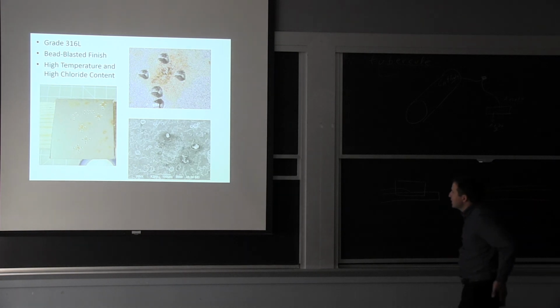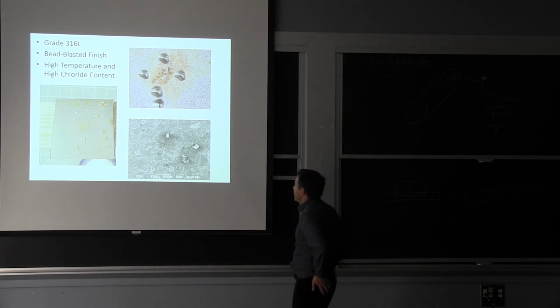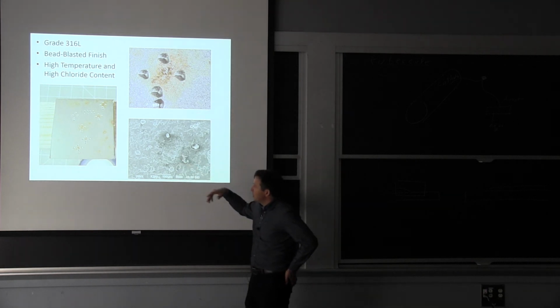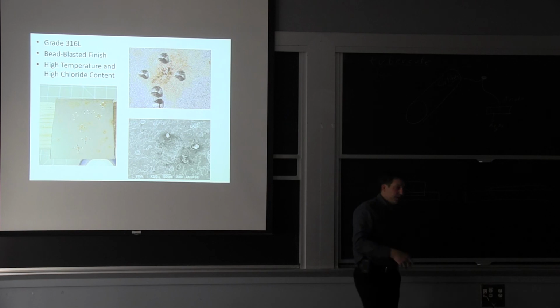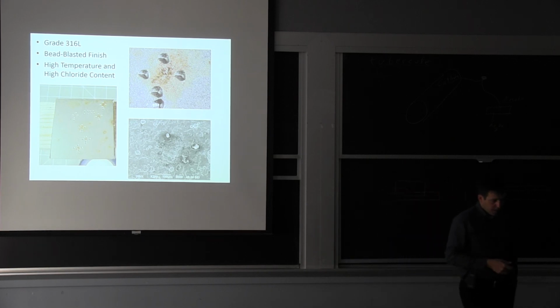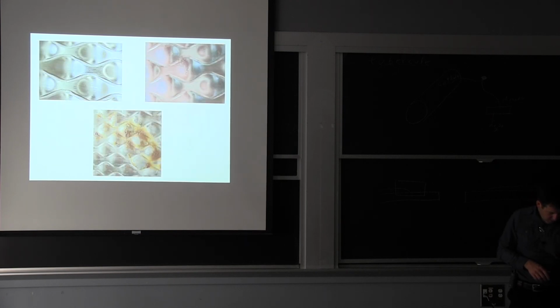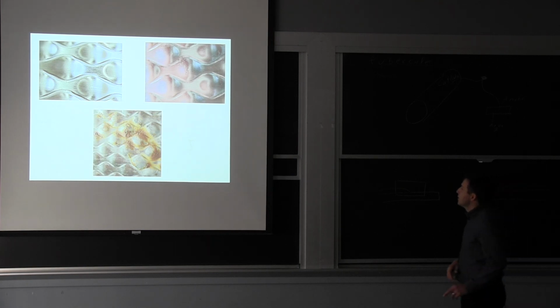This one just shows a little example of that pitting at the very small scale. When you have these holes, after you've pitted for the first time, even if you clean up and you put the coating on, what I found on a number of projects is you're still more likely to pit again, because you created these sites, these holes that are likely to continue over and over again. You can see a few of them here.